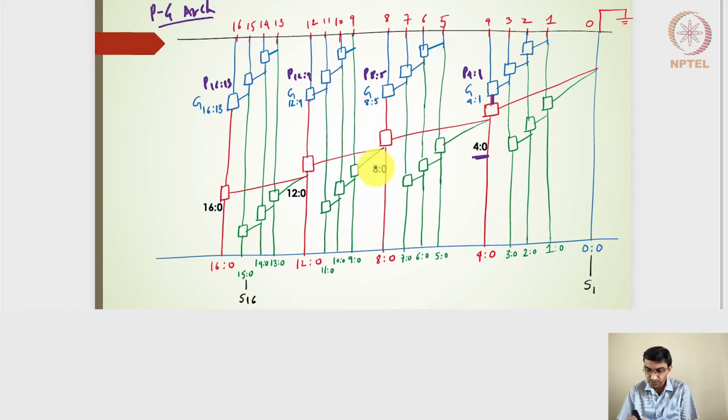subgroups here. So without even worrying about 7:0, 6:0, and 5:0, which are actually useful for generating the sum 8-bit, sum 7-bit, and sum 6th bit, without even actually generating this, it is actually generating 8:0. So it is actually looking ahead. It is actually looking ahead to 16:0, without even considering when 15:0, 14:0, 13:0 are generated. And that's why it is called the carry look ahead adder.